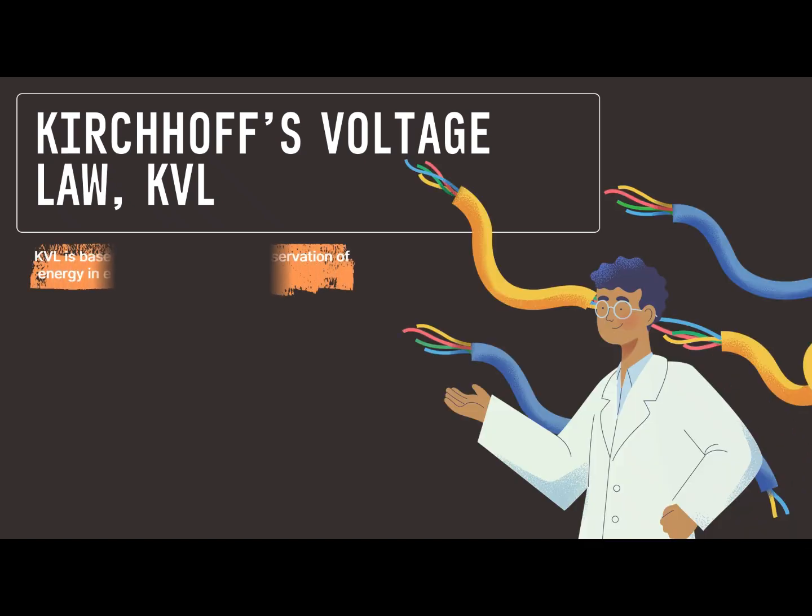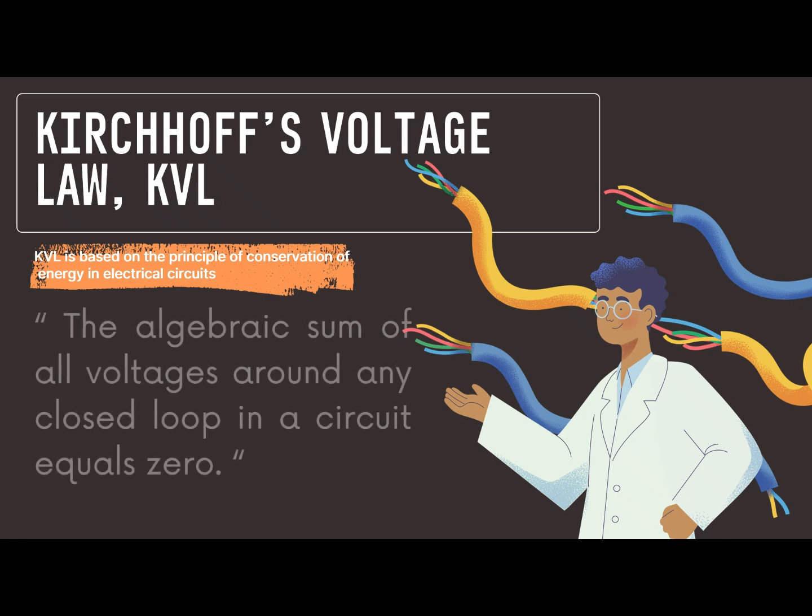KVL stands for Kirchhoff's voltage law. It states that the algebraic sum of all voltages around any closed loop in a circuit equals 0. This means that the total voltage supplied by the source must equal the total voltage drops in the circuit. The reason for this is the law of conservation of energy, which means energy cannot be created or destroyed in a circuit.